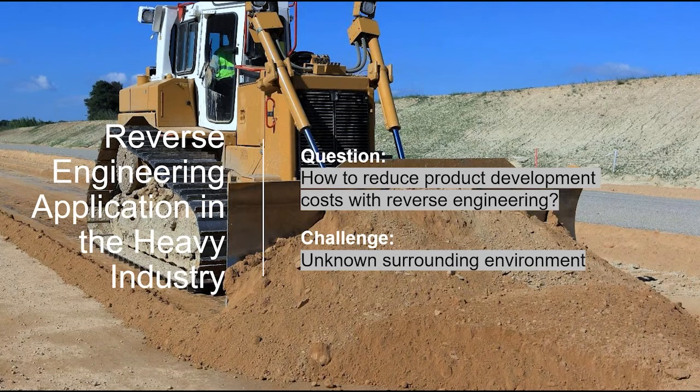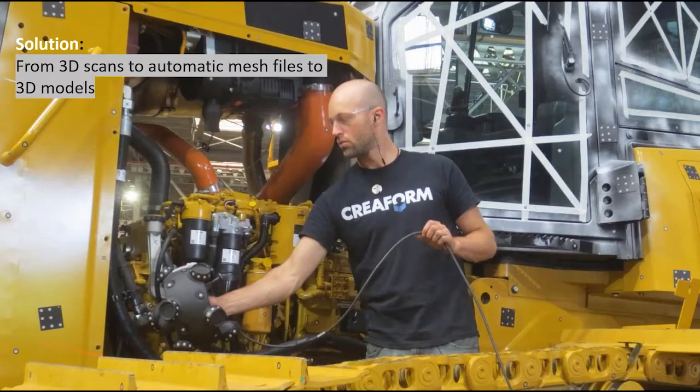Another challenge here is to measure accurately spacing or distances between different objects or fixture points. So often direct distance measurements are impossible since there are different components blocking the way. This can lead to inaccurate measurements or a long measurement process if these components have to be removed. So here again, using conventional measurement tools is not an efficient solution. Instead, using 3D scanning will help to gather 3D data of all the surrounding environment, a process that would otherwise be lengthy using traditional measurement tools.